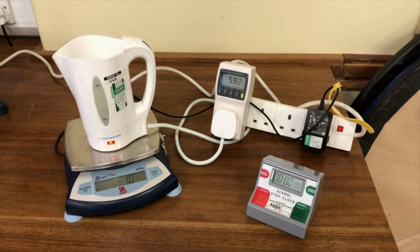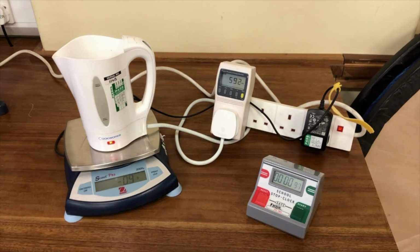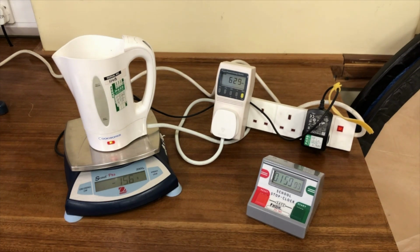This is the apparatus you can use to measure the latent heat of vaporisation of water. We place a mini kettle on top of a top pan balance with the lid removed so that it continues to boil. If you reset the top pan balance at the same time as starting the stopwatch, water will boil away from the surface of the water in the kettle and the value on the top pan balance will decrease. After about 1 minute, 75 grams of water has boiled off from the surface of the water, and this value can be used to calculate the latent heat of vaporisation using the equation.